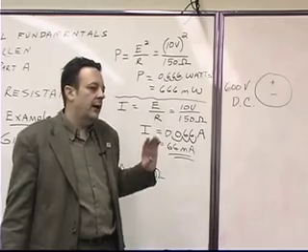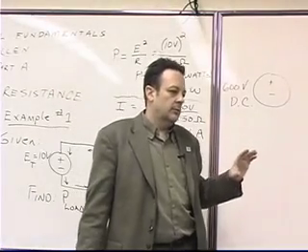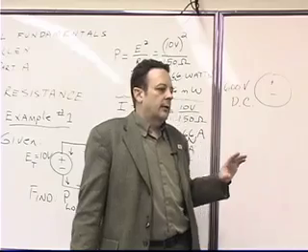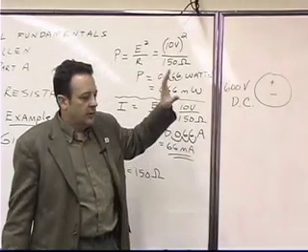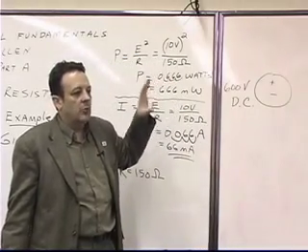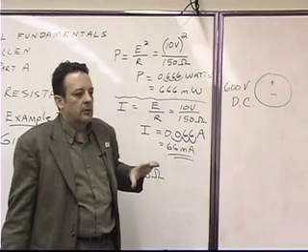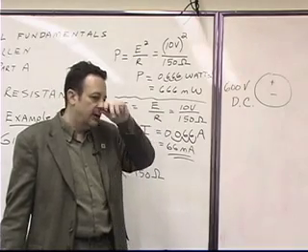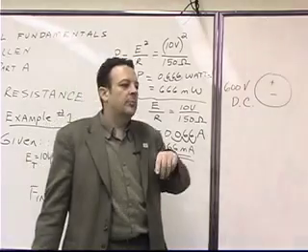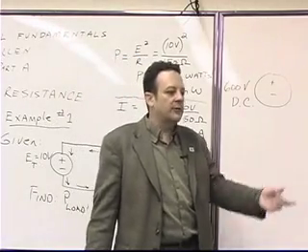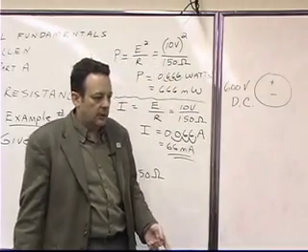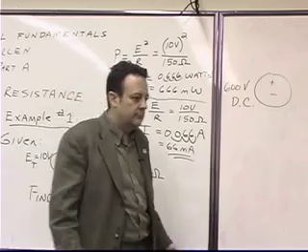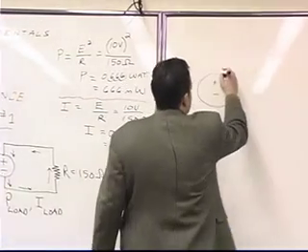Okay. So the solar panels have to be converted from DC. No. The solar panels put out direct current. Yeah, they have to be converted from DC to AC. Right, but in this particular example, I'm just showing an example where we're not going to do that. We're not going to convert it to AC, and the reason is because the pump motor that we have runs off DC. Okay, and you can buy pump motors that run off DC.